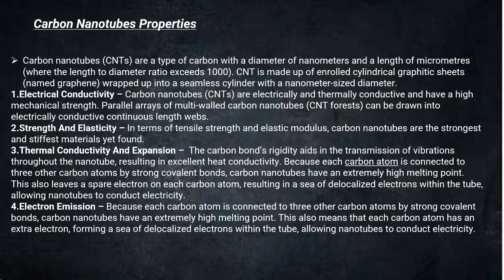Carbon nanotubes properties basically are thermal conductivity, electrical conductivity, and it also depends on aspect ratio. And CNTs are very elastic, with 18% elongation to failure. CNTs have very high tensile strength, and they are also highly flexible, and can be bent considerably without damage. CNTs have a low thermal expansion coefficient.